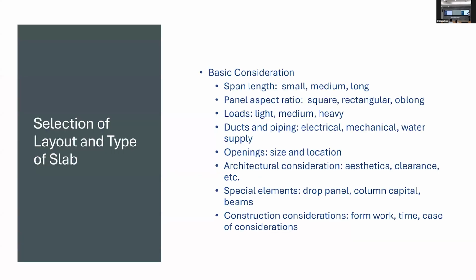But in many cases post-tensioning may not be possible, may not be available, or may not be approved by the authorities, because flat plate, flat slab is not allowed by the code for tall buildings for carrying lateral loads. It has no frame capacity, so it cannot be used in a seismic zone without another system. So it's still problematic. You have to prove that the system will work without the frame action. We'll come to that later.